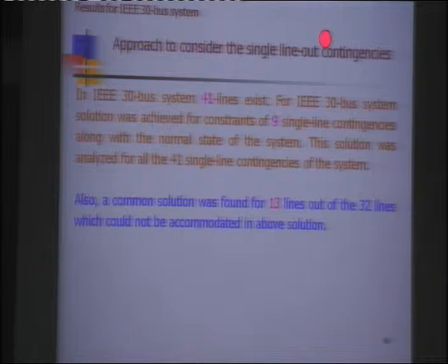For example, in a system there are 41 lines. For example, 4 lines are gone. First of all, the solution has to be found with all lines in consideration. Now suddenly 4 lines are gone. Your protection setting should satisfy the present fault also, if it occurs in the remaining section. But normally it is found that this setting does not fit the new structure because of the fault.